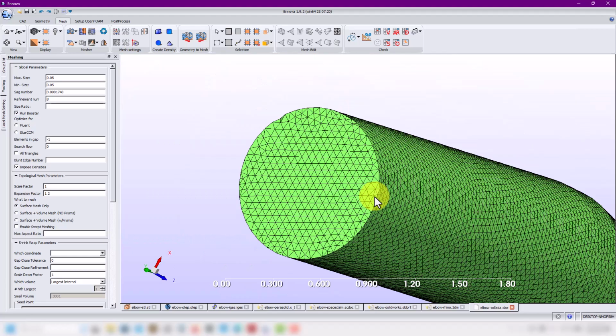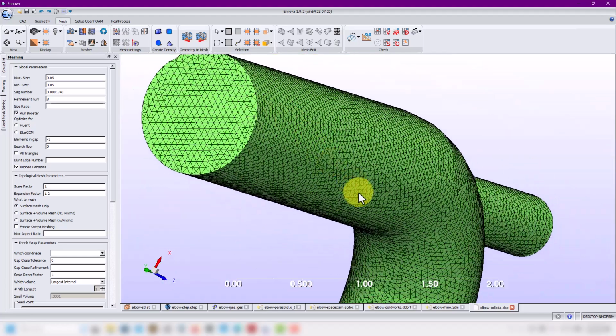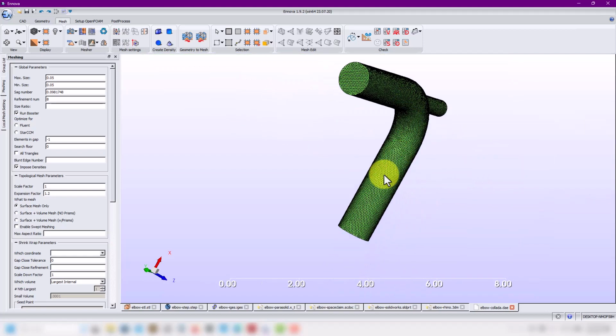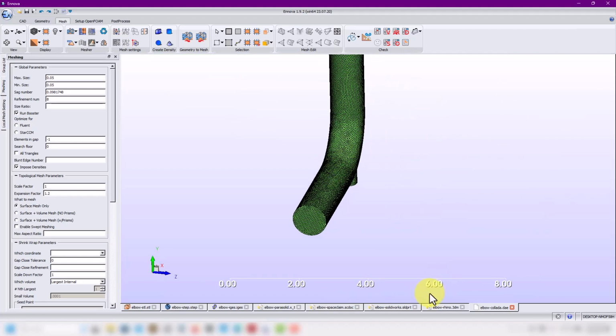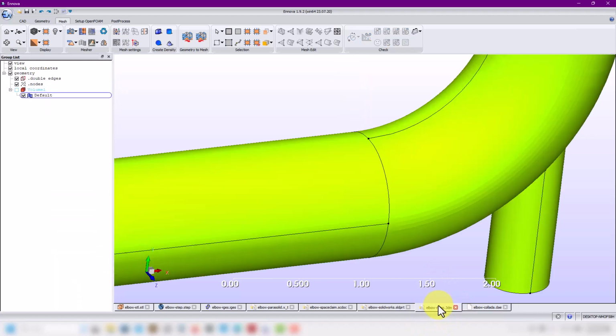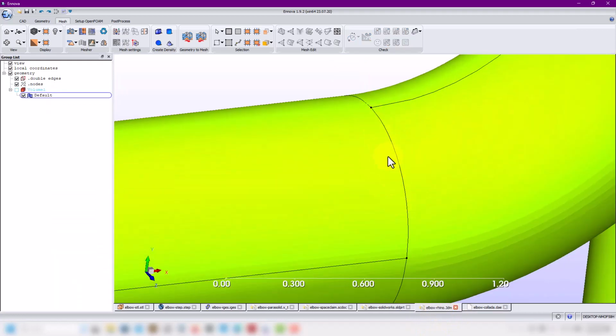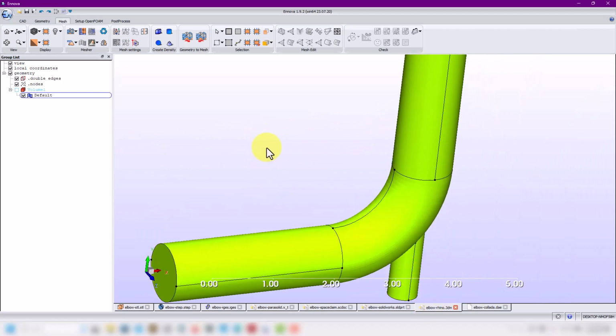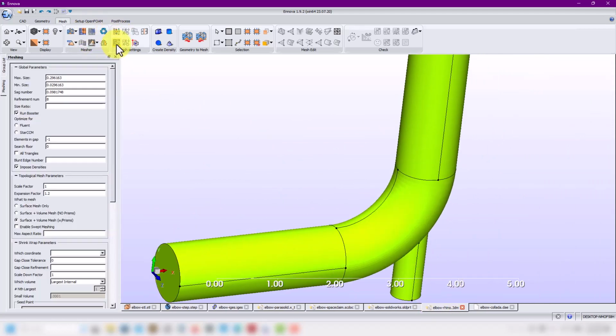But the idea is the mesh needs to be economical, okay? I cannot have a 1 billion cell mesh to resolve this problem, okay? It makes no sense. So look at what happens when I use a mesh where I have a geometry, where I have all that topological information. So I will pick this one, doesn't matter, okay? And I will apply same parameters, okay? So let me use here 0.05, 0.05, and on the surface meshing.